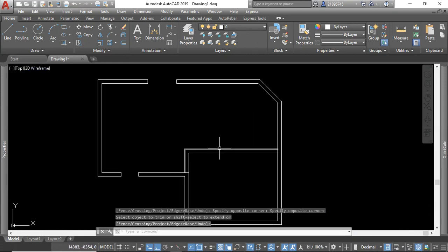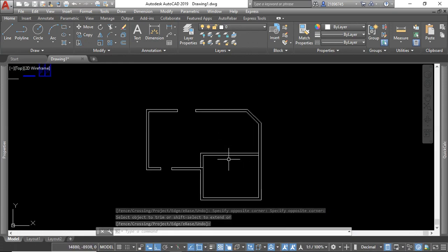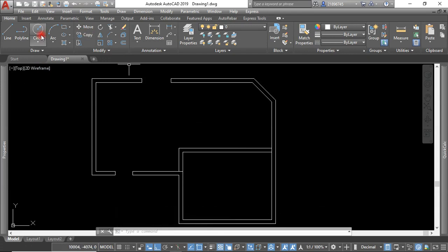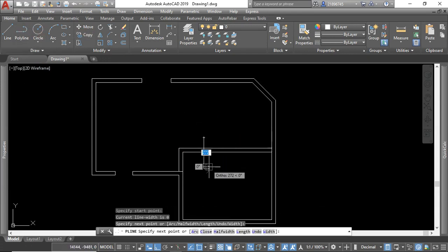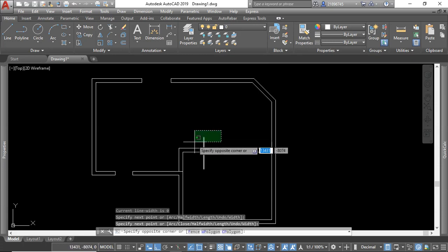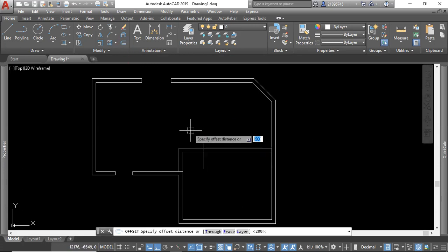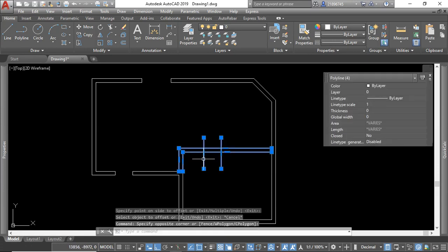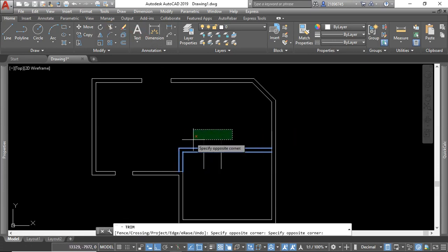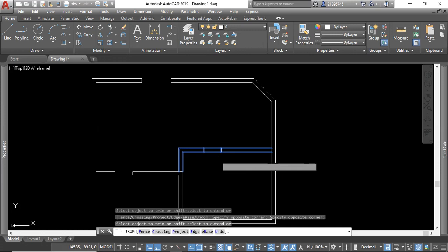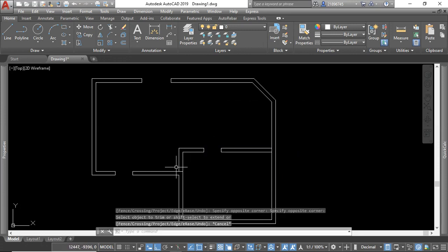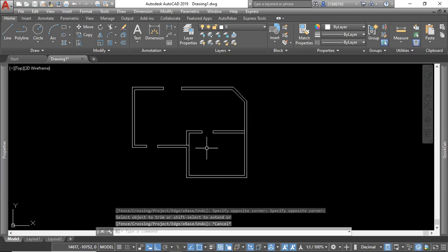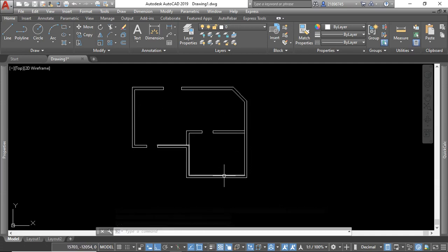we go enter. The other thing, maybe we can create another door here. We do the same here like this, then we select, we offset by maybe 900, then we select everything, then we come here, we trim like that. Maybe we can have a window here, the same.